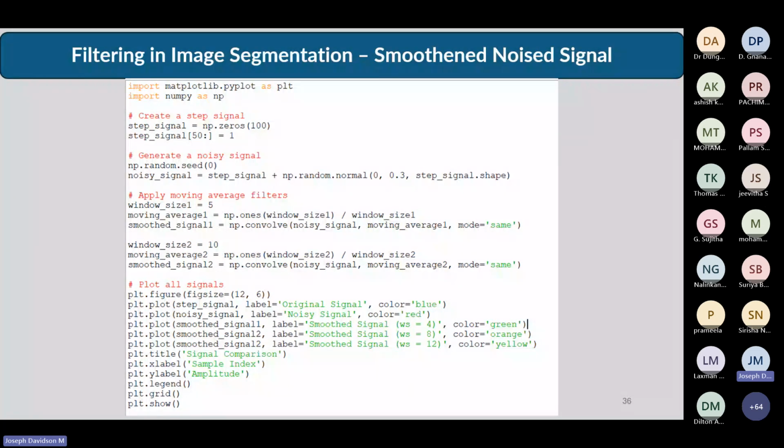One such filter is called the moving average filter. The signal varies randomly from the left side to the extreme right corner. This algorithm takes a particular window of values. There are different types of moving average methods: 3-point, 4-point, 5-point, like that.